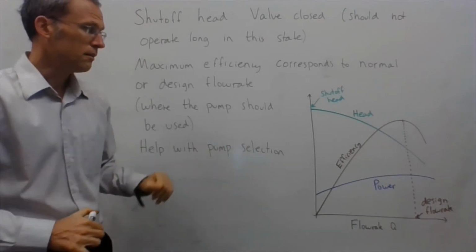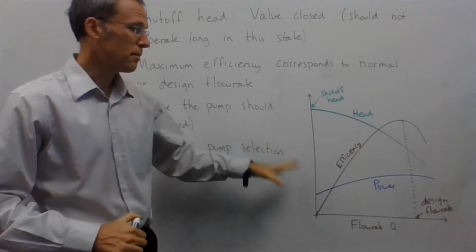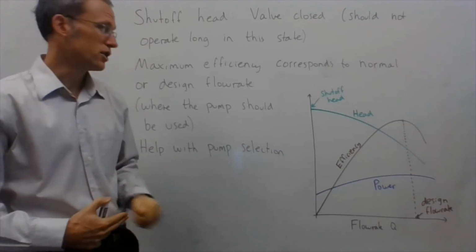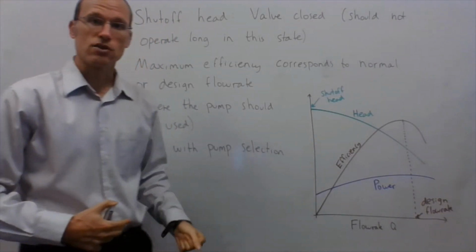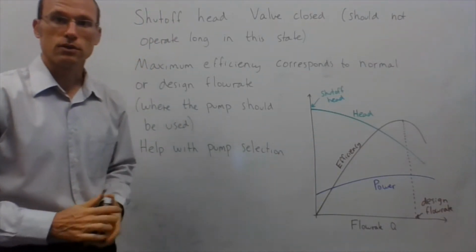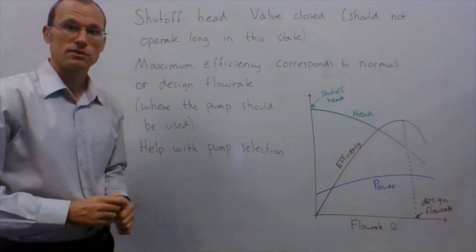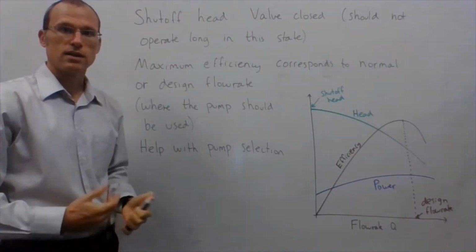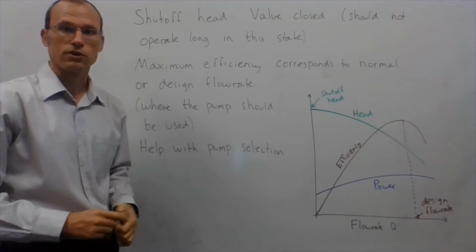And again, it's not just which pump to use, but also what rotational speed, because as I mentioned, these curves are all going to change based on rotational speed as well. So this matters both for the actual pump itself, as well as how fast to turn the impeller.